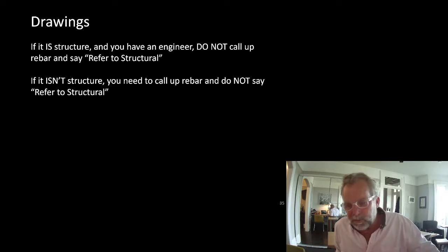If it is not structure, that is, if it is paving or if it is a curb or something that is not a designated structure under the building code that requires it to be engineered, then you as the landscape architect need to call it up. You need to call up the amount of rebar that it needs for crack control and whatnot. And you do not say refer to structural.